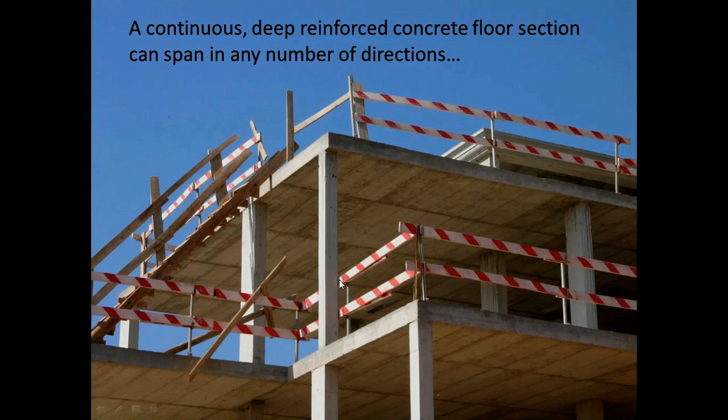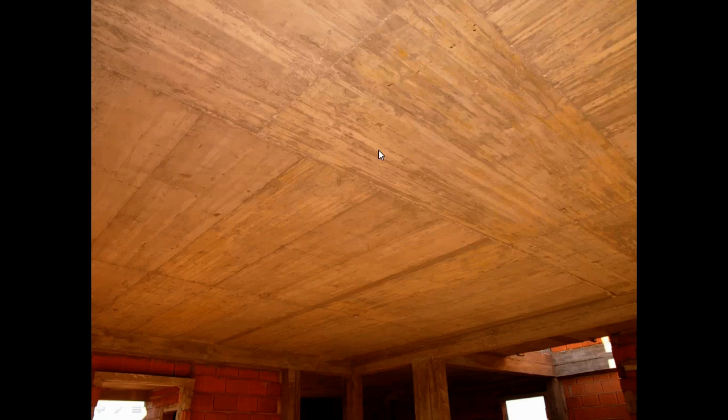Okay, you can almost see here, there are columns on the corners pretty much. Oh, there's a deep one. We know what that's doing now, don't we? Resisting the lateral load. And there's another couple of them in the middle there, but they're sort of a little bit all over the place, which is useful. There's the underside of that floor. It's very simple. It's kind of common technology throughout the world.